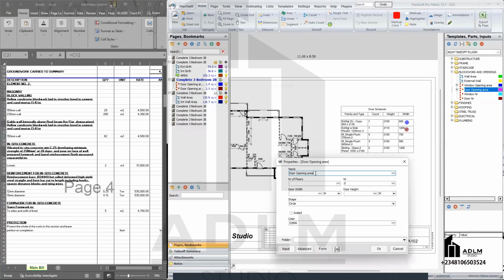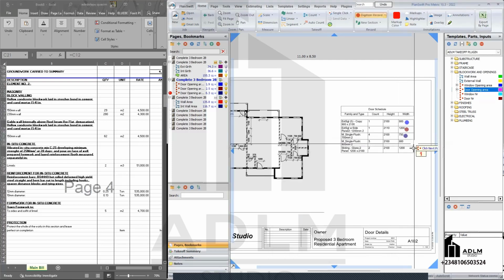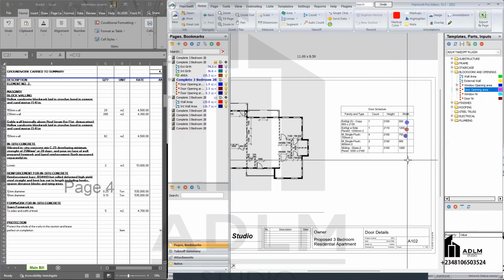Then the next one here, which is the third one, just turn this on. That's for 3. Number of floors is just 1 floor. Now the width is 0.75 and the height is 2.1. Now this has an option here. If you just want to click on single points, this is 4 numbers. I just change these numbers here, just change to 4, click on OK, and just click on this point. That's all, then just stop. So that's all for that. We've done 4 of this already.